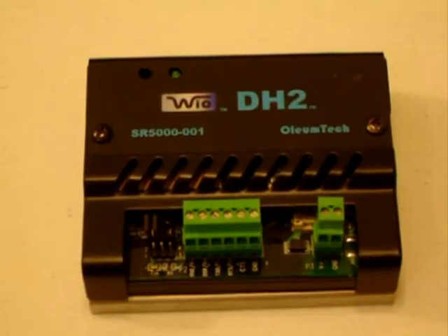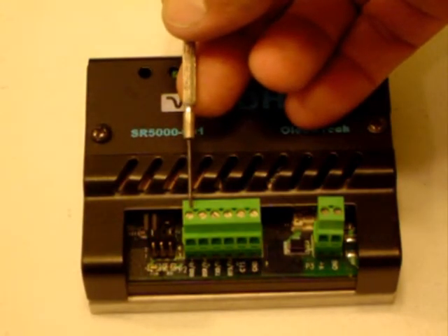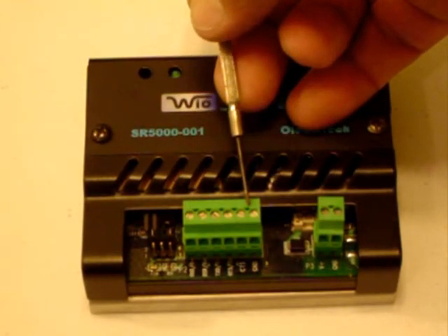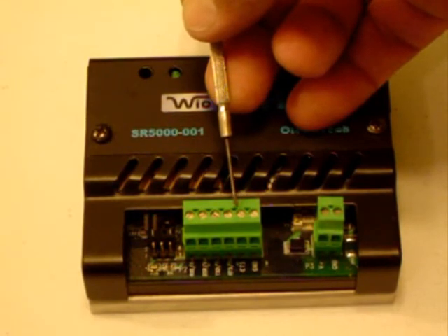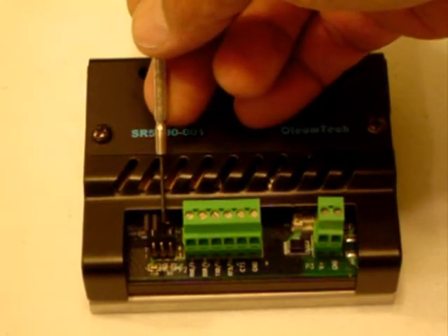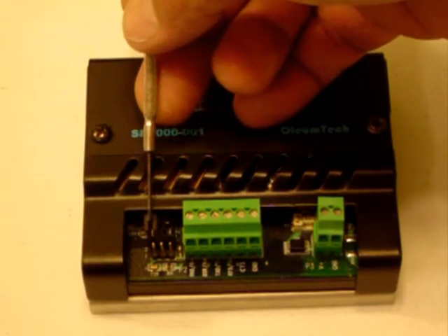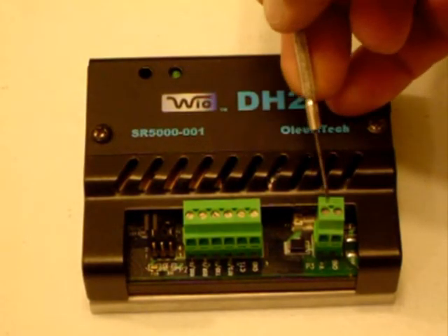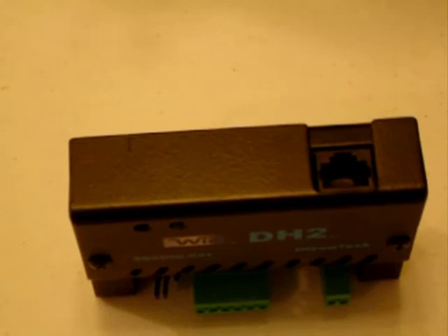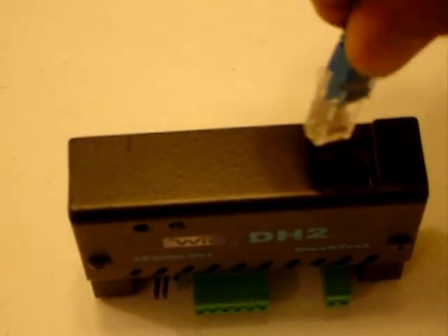The connections for the DH2 are a Phoenix connector in the front for 232 or 485 communication wiring to interface to your Modbus master. You also have jumpers beside this connector that must be installed if using RS-485. You also have power and ground connection. On the back of the DH2, you have your configuration port, an RJ jack, which is used to download your configuration from Breeze. On this side of the DH2, you have an MMCX connector, which is used to connect your antenna. And that is all the connections of the DH2.